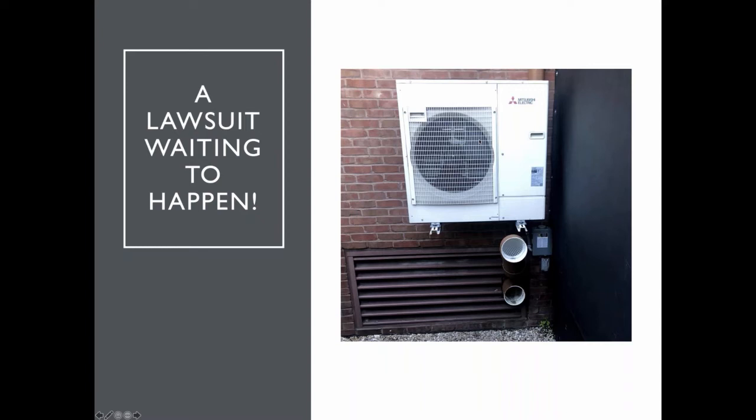Well, how about this one? There's a wall right here, and they have the boiler outlet here. This is the combustion air right here. This is the air for the space for ventilation air. And so this is a lawsuit waiting to happen. That combustion gas is going to come out and get pulled into here, or even ruin his brand new VRF system.